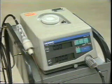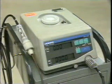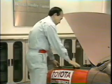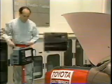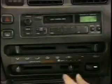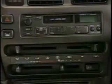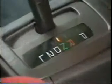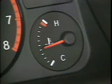Now, let's see how to adjust the idle speed and mixture. You should use a CO meter to do this if possible. First, in order to adjust the idle speed and mixture properly, we must make sure that the following conditions are met. Make sure that all the electrical accessories are turned off. Check to see that the transmission is in neutral. Make sure that the engine is warmed up.